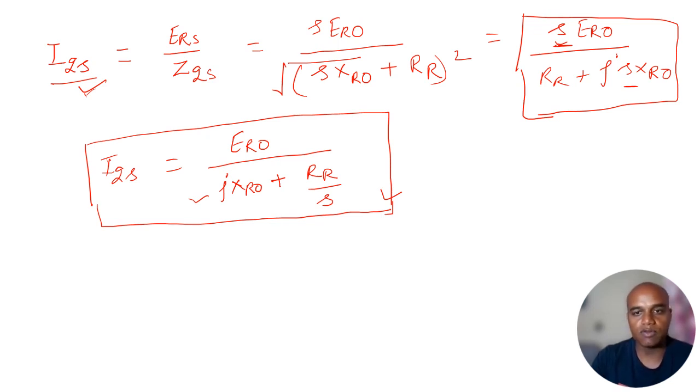So whatever is developed by the primary circuit of the transformer is transferred to the secondary circuit. So we don't have any function of the slip over here. Similarly, the reactance is not part of my slip. The only thing which is varying is the resistance of my secondary circuit, because it becomes a function of the slip. I can easily correlate this with my transformer equivalent circuit diagram, where the secondary resistance can be varied by the external load: if I apply the load, the secondary load changes, and then the resistance also changes. So this is okay for me.